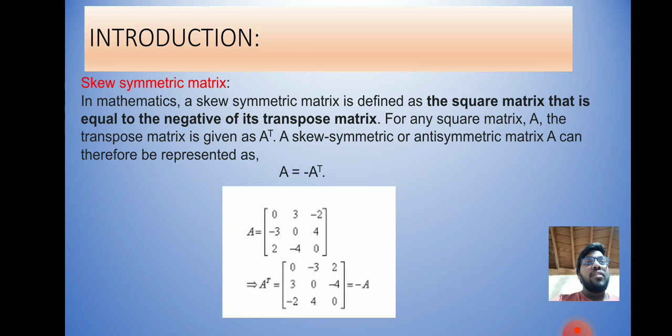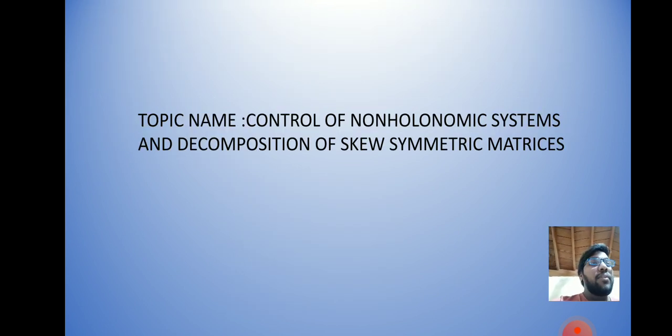And here in the topic we have non-holonomic systems. What do non-holonomic systems mean? Let us know by example. A simple example of a non-holonomic system can be a wheel that rolls on a plane surface, such as a unicycle. The constraint here arises due to the roll-without-slip condition. The configuration in the generalized coordinate vector is q is equal to x, y, z. Next we discuss